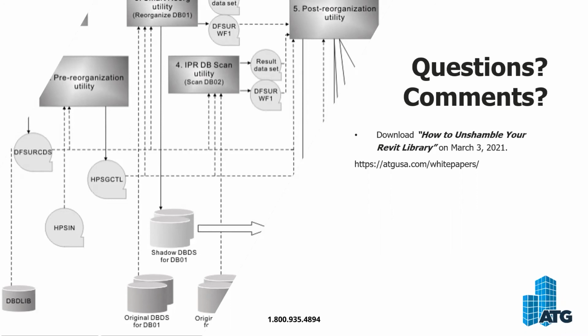Let's see, Dania has written some Dynamo to add and set parameters. Yeah, and she also mentions there is a CTC. There's actually a couple of CTC tools for pumping shared parameters into content. I kind of got to caution you about that too, though, because there's some firms that will turn their users loose. Okay, you guys go to Revit City or wherever you want to go, grab the content, but at least use this CTC parameter jammer and push those shared parameters to it.